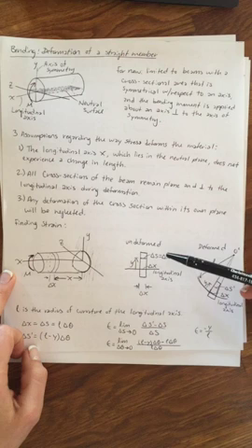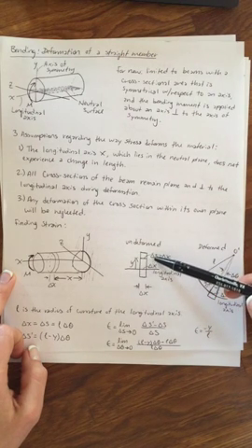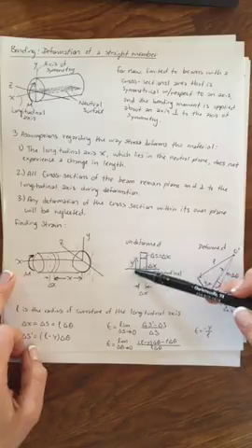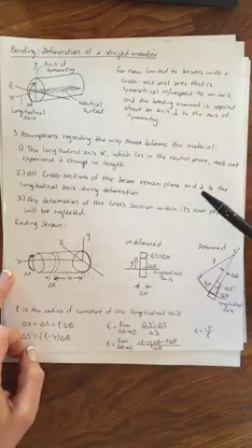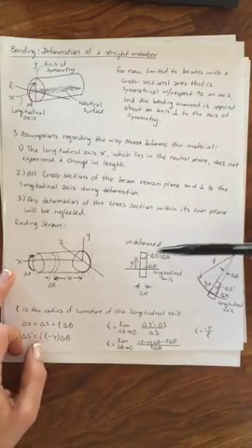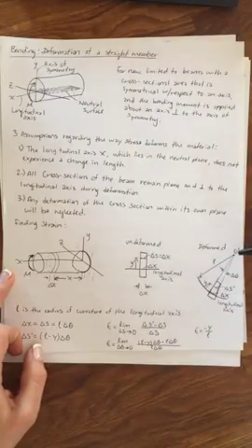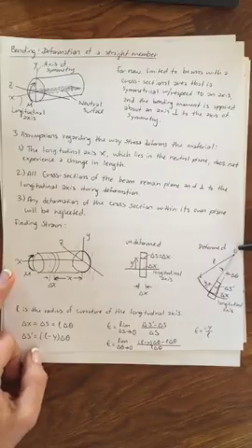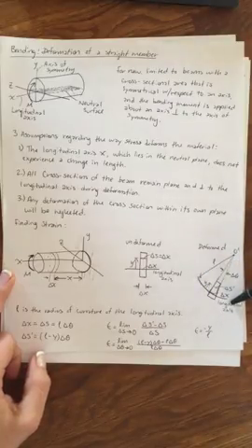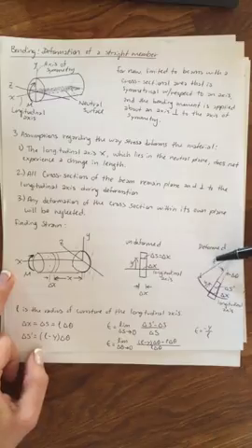y is the distance of any segment s that we're examining, the distance from the longitudinal axis to that segment. And then delta x is, of course, the width of the differential we're examining. So this is the undeformed state, and when we think about the deformed state in terms of that moment and the action, we can designate this distance, rho, from the center of the curvature to the longitudinal axis, which is now curved, and rho is the radius of the curvature of the longitudinal axis.